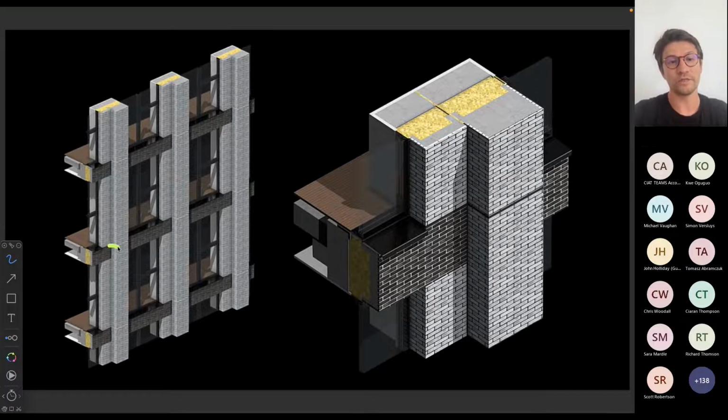You're still going to see the joints in here, but they will not be as visible as you would say in the unitized facade. And again, you don't see all these joints in the corners and between the recesses, because in the corners, the joint becomes automatically concealed. That's when the building is fully prefabricated.